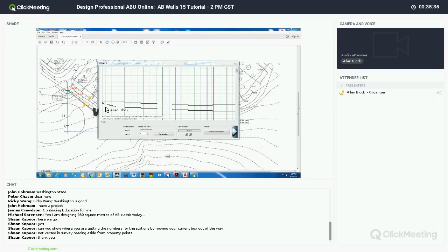So on this page, our actions are that we're going to cut our wall into panels, and then we're going to take one cross-section for that panel. We're going to decide our panel cuts based off of geogrid roll widths, and that's what these green lines are representing. They are representing the end of a geogrid roll, so it's a constructability standpoint for our contractors. So if you have to change grid depths at a certain point in the wall, we're doing it at the end of a grid. Less waste on the site and less cutting for them to have to do.